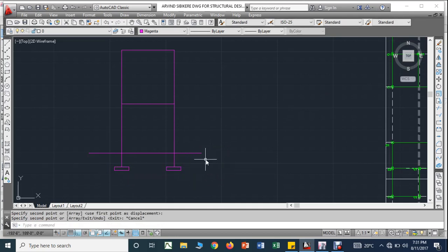But you can see here, students, in the software we have not given this dimension. This is the roof beam of the first story. This is the roof beam of the ground story. And here comes your plinth beam, that is at the ground level. Below the ground, you have some column, below the plinth beam. So this depth, that is your depth of the foundation, we have not taken.